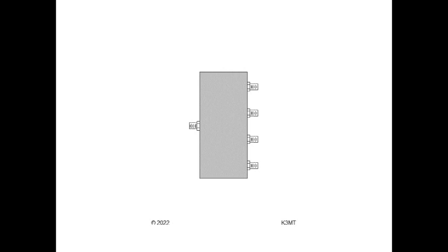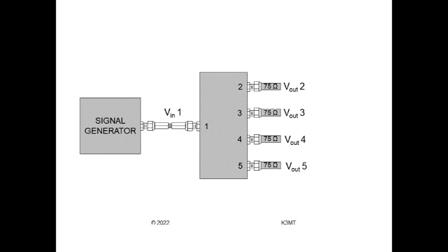Let's see how much. Number the ports, 1 to 5, with a marker pen. Though a strong bias tends to number the input 1, it really doesn't matter. Put 75 ohm loads on all the others. Then, connect port 1 to a signal generator at a constant frequency. S parameters change with frequency. Put some voltage, perhaps 75 mV, into the splitter. Then measure the voltage across every load.